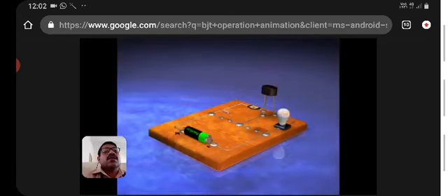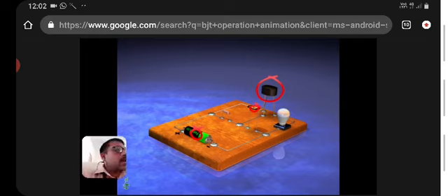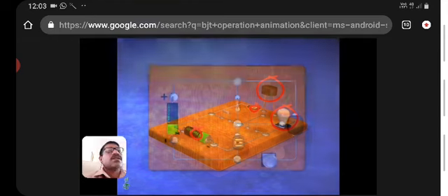Now let me show a small circuit of this street light. The battery is shown in green, the transistor is the black one, and an LDR is represented here. The LDR is nothing but a light dependent resistor. When the illumination is less, the resistance is more.